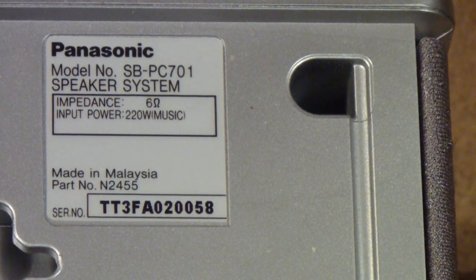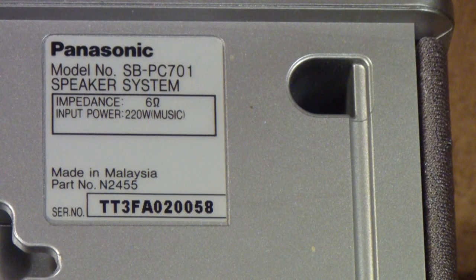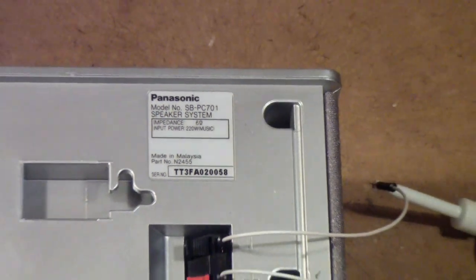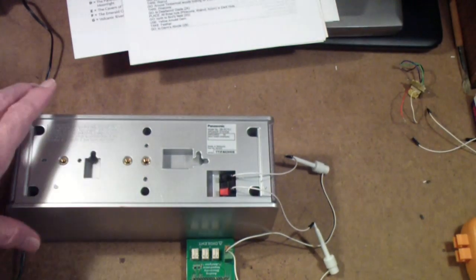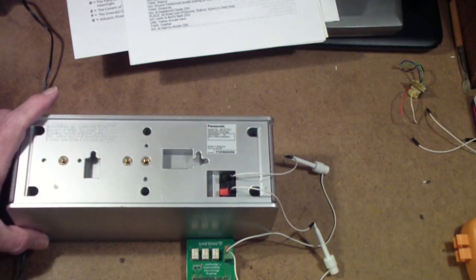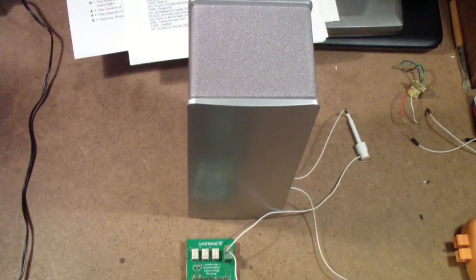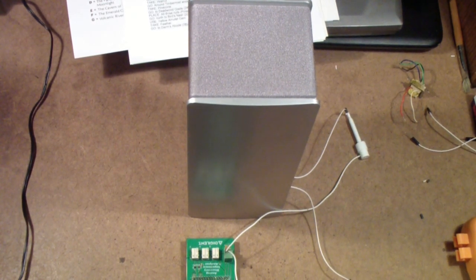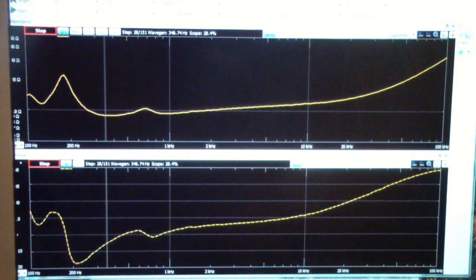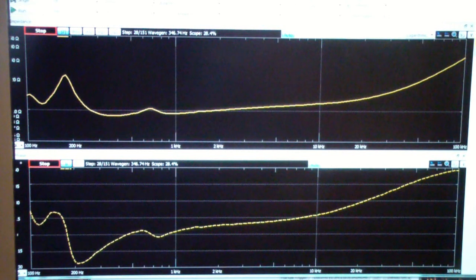So let's go look at what we actually got on the waveforms display, but before we do, I'm going to stand this speaker up because that way we can run it in the other position to get a comparison. And what I'm trying to demonstrate is that the environment of the speaker determines to some extent the impedance it presents to an amplifier. So let's go look at waveforms. So here's the display. This is the waveform software that comes with the Analog Discovery. Let me move this out just a little.